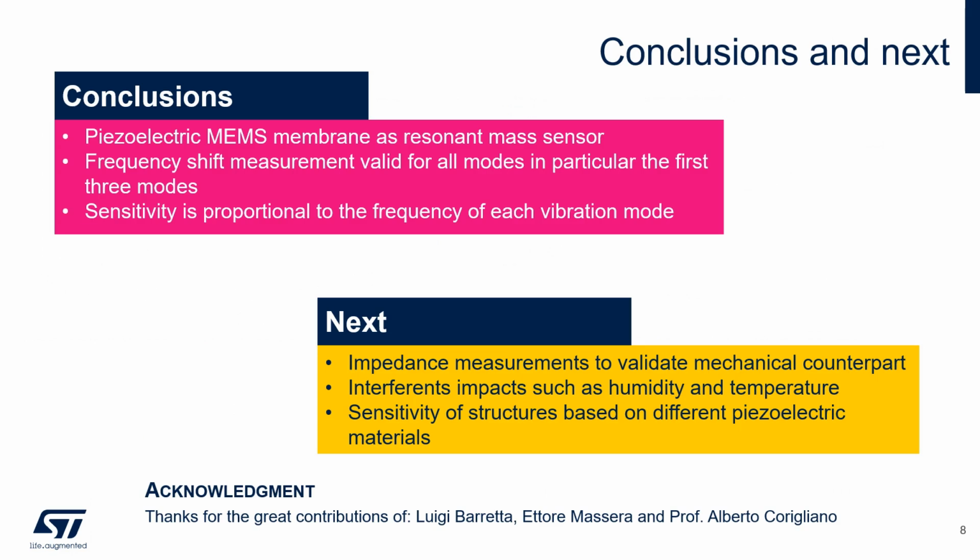In conclusion, we showed that piezoelectric MEMS membranes can be used as a resonant mass sensor. In addition, the frequency shift measurement is valid for all modes, and in particular, we focused on the first three modes. And the sensitivity is proportional to the frequency of each vibrational mode.